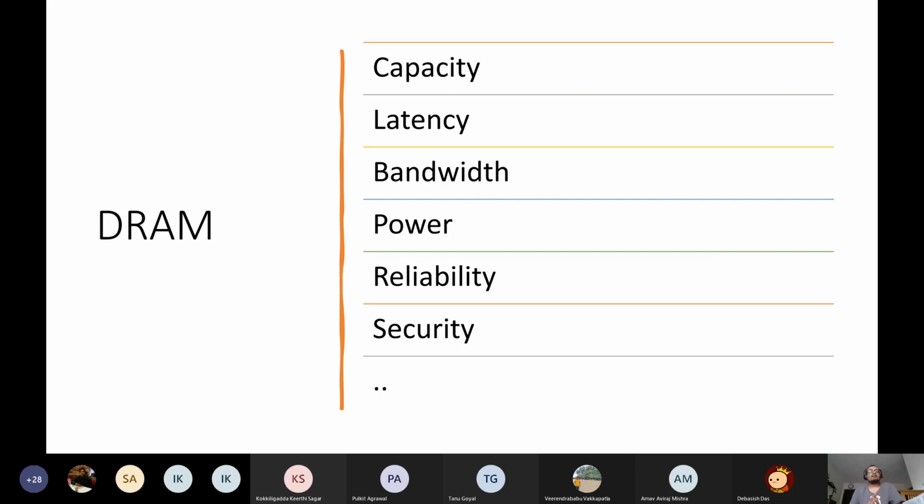That's why latency is not the primary citizen, and that's why you will find DRAM latency is higher than on-chip caches and other structures. There are various other reasons, but you can easily correlate with the kind of circuitry used for DRAM and the low frequency used to operate DRAM.